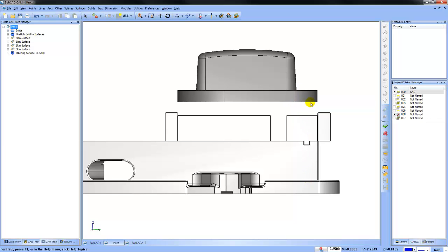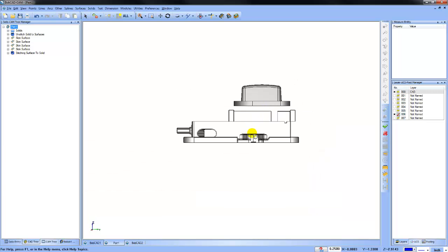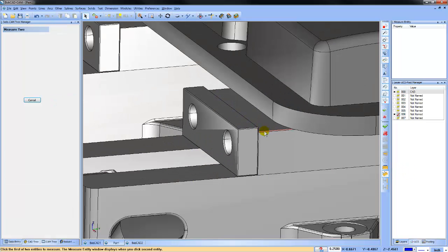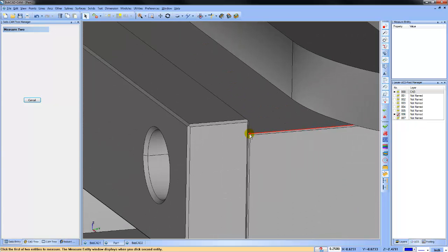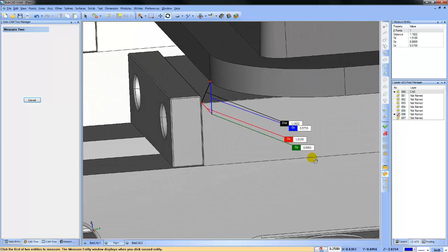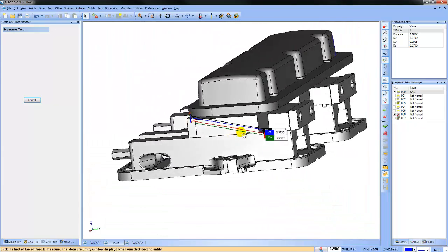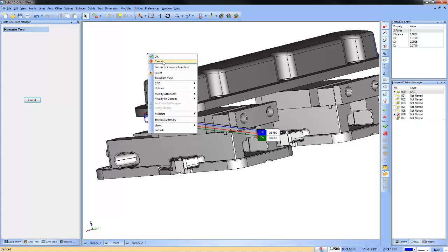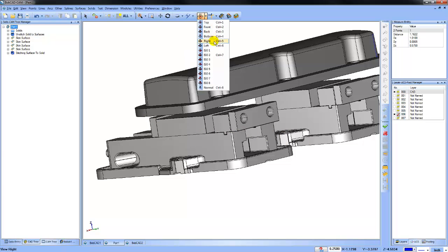the spacing for this, to get this on this face here or mated with that face, there's some measurements that we need to do. So what we're going to do is just go to measure 2, and then we can click on this one here, and we'll grab this edge, and then we can click on that one there, and we'll grab that edge. And then what that's going to do is figure it out for us. The value that we want here is the Z value, so we can actually just take this value and copy, and then cancel, and we'll go to a right view.